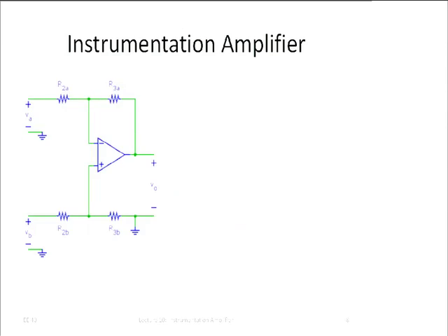Okay, so there we have this solution. Here this is the other half of the circuit, and actually this half of the circuit, V out over VA minus VB, I told you that we had solved this already, so go back in the lecture notes. What you'll find is minus R3 over R2. Okay? And then afterwards I simply have to put them together.